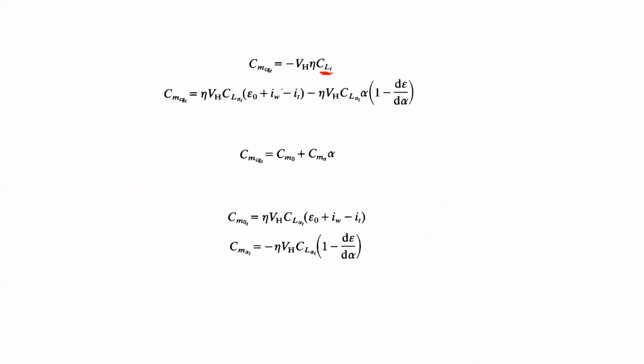So when we take things, we separate things. So this appears constant with respect to angle of attack. Remember, it changes from aircraft to aircraft. For one aircraft, it will be fixed. Now, this number is dependent on angle of attack. All right. So this whole number, apart from this angle of attack, you take the angle of attack out, you call the whole quantity CM alpha. It's written here. So this whole quantity CM alpha is the pitching moment slope contribution from the tail, and this is the CM naught part, which is this constant part.